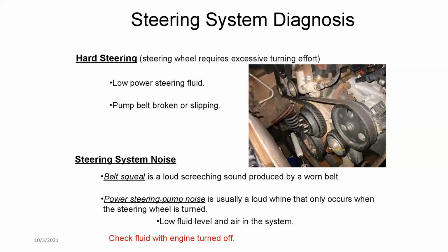So every time maintenance comes into hand, we usually always consider the most possible thing and the least catastrophic or the least worrying thing. For example, in this case, hard steering, the first thing that should come to your mind, as if you are maintaining a vehicle, is that the vehicle should be having less power steering fluid, right? That's the first thing that should come into your mind.